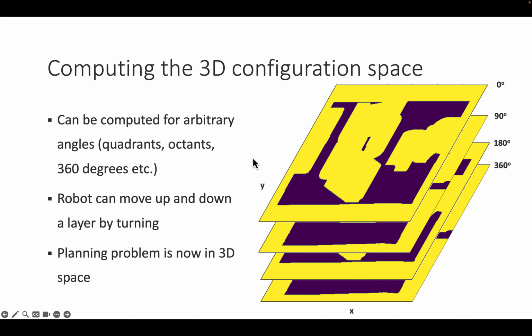So the important step here is we forgot about maps, which are just display relevant information, and talked about ways to make the maps actually useful to navigate on them. How to navigate is a different story. We will talk about this later, but I want to conclude the mapping theme by pointing out to you that the actual map is a map that is useful for navigation, and if I have to do a lot of collision checking, this is much less useful than storing a data structure that I can use directly as a topological map graph and feed to a planning algorithm.